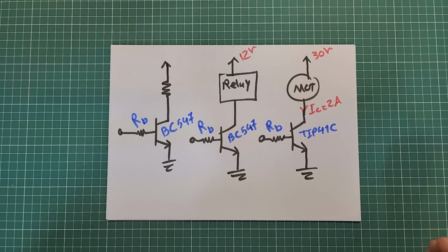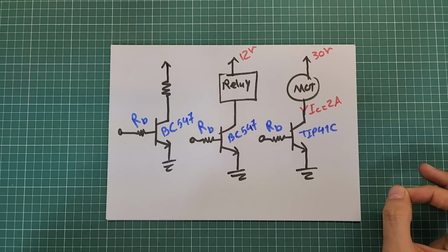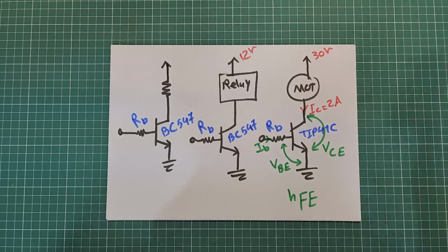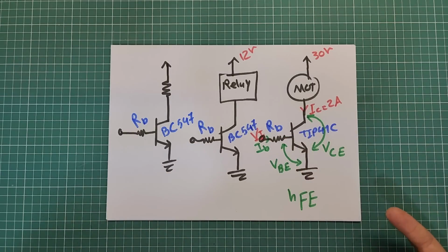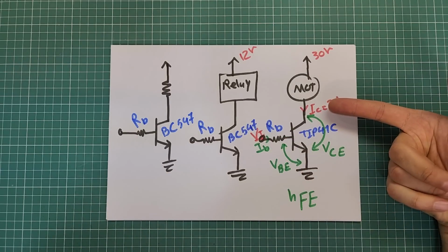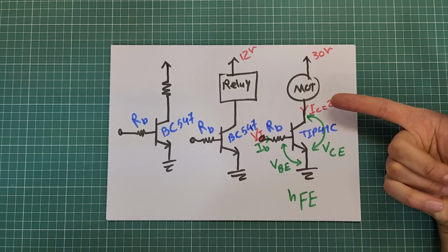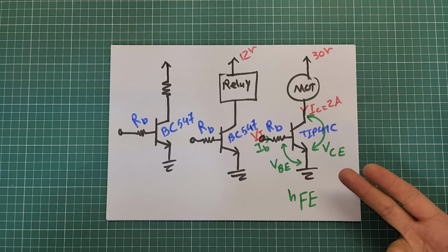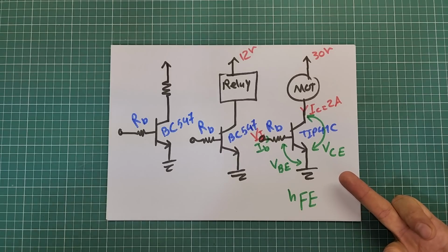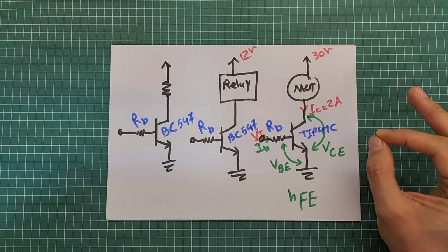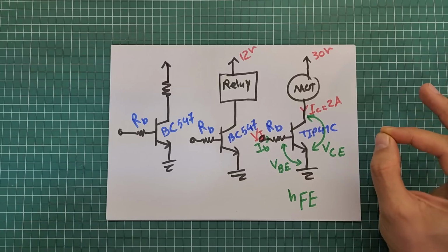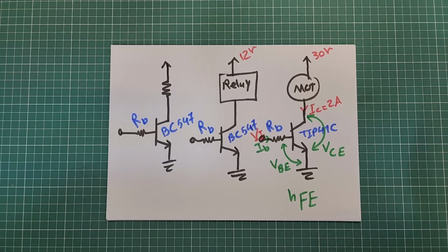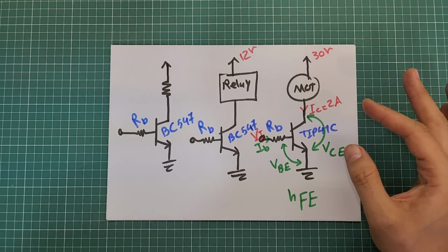The first method for selecting the best base resistance is the simplified method. These are the parameters needed to find the best base resistor. IC, or collector current, which is almost equal to the current rating of the load. I mean the maximum current drawn by the load. VCE, or collector emitter voltage, which is usually considered to be very low, say 0.2 volts or even 0 volts for simplicity. VI, the input voltage, which is the voltage that is going to trigger the base terminal.